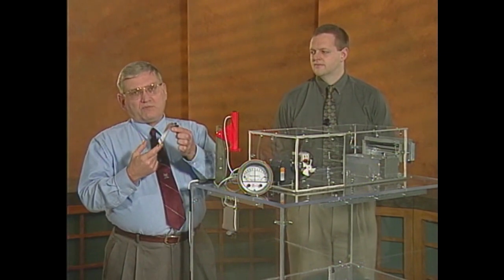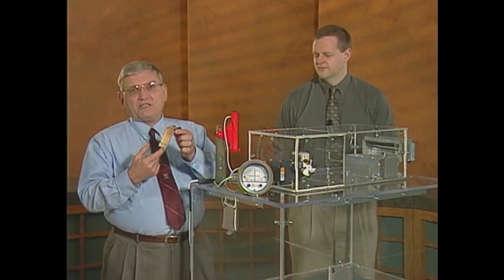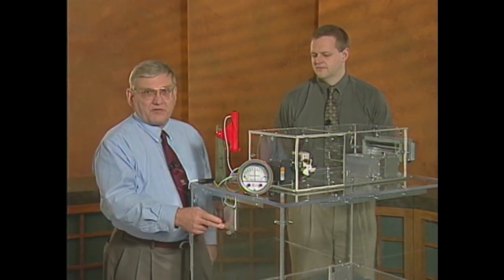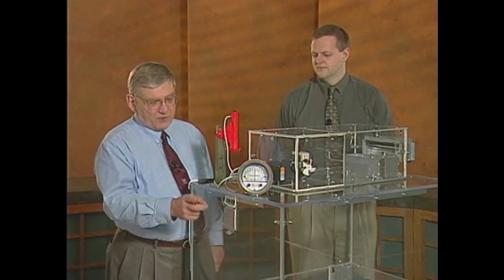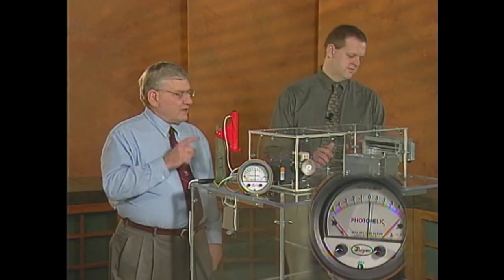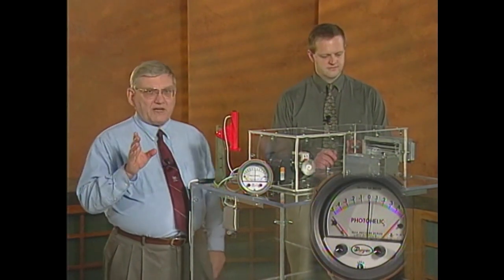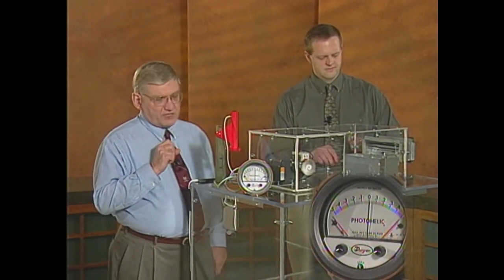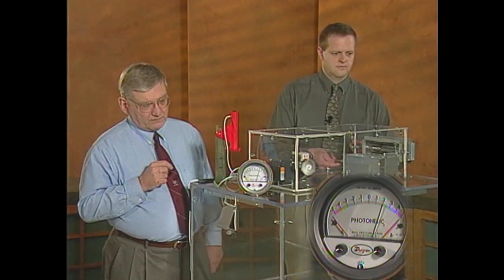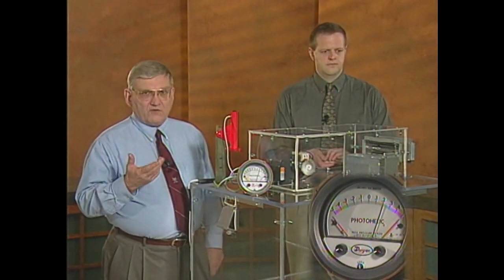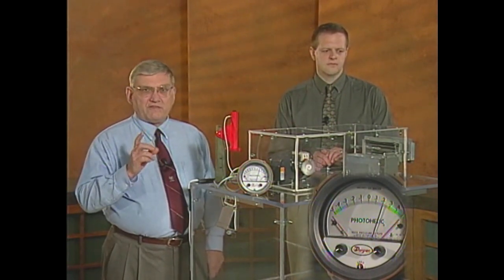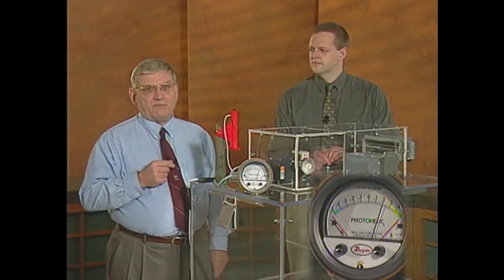So when the damper is fully deployed, it requires about 2/10 of an inch static pressure to open the damper fully up. Now, we placed one of these local barometric dampers in the building wall. We can show you how it works. Let's turn on the supply fan. Right now we're at 0% outside air. Let's go to 100% outside air. Watch the pressure gauge and the barometric damper. Fully deployed, the barometric damper is open. Building pressure increases by just 2/10 of an inch, not 5/10 as in the last example.